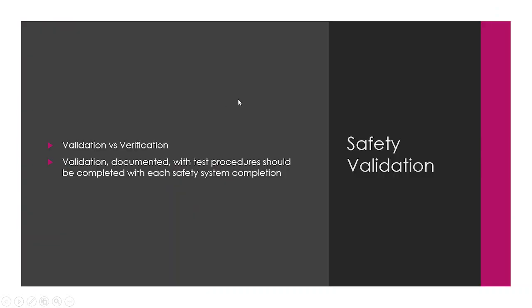And last but not least, the most important thing is once you've completed your system, you need to redo your risk assessment to verify that you have met all of your proper criteria to make the machine or the equipment safe. And you need to validate and verify. Validation is a documented test procedure that goes step by step, verifying that each one of the pieces on your validation is up to par with what your requirement is.